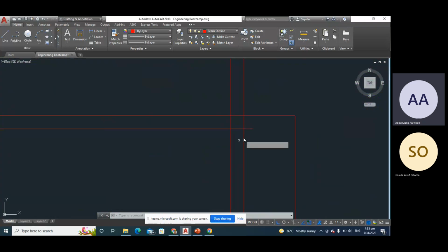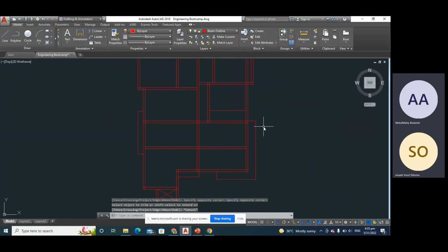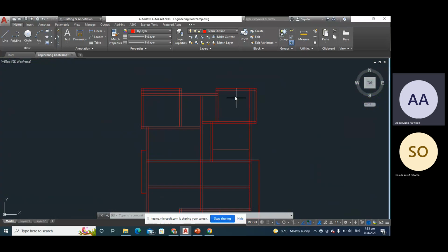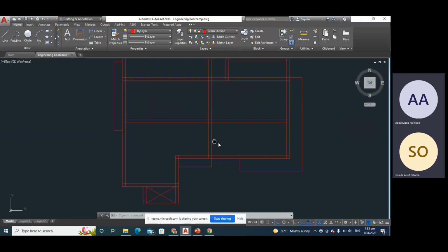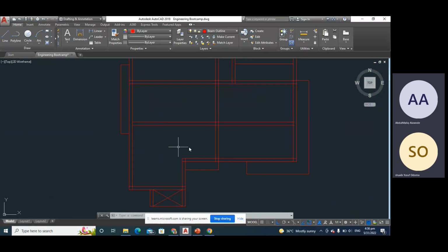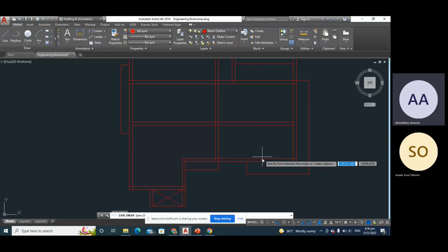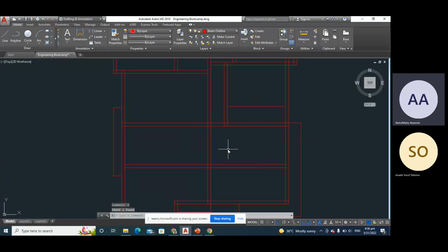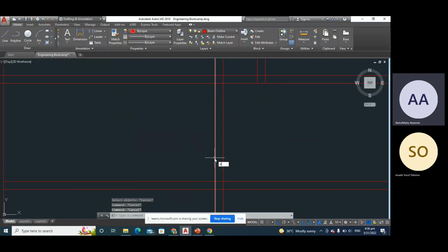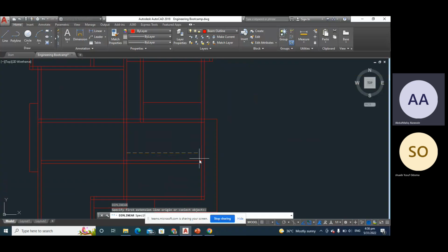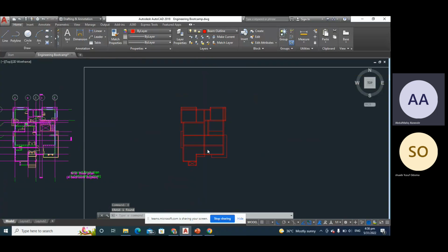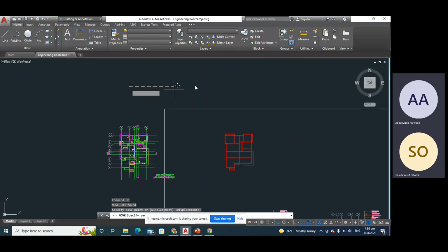So let's question our GA. Is it okay? We have analyzed this place yesterday, last week. Now this place, is it okay? It's fine. Is this slab okay? It's fine. This slab also is fine. Can we eliminate this beam? If we eliminate this beam, what's the implication? From here to here is 5.6. From here to here is what? 5.6. So a 5.6 by 5.6 slab is a two-way slab and it's not much.